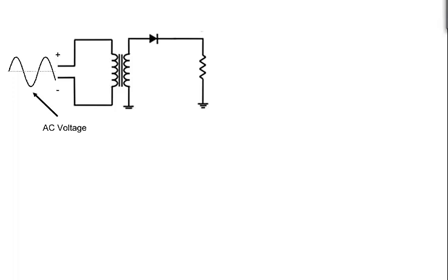The input is an AC voltage. If a transformer is used, the input voltage is applied across the primary winding. The output is a DC voltage because it does not reverse polarity. Unlike the output of a battery, however, this voltage doesn't have a steady level.